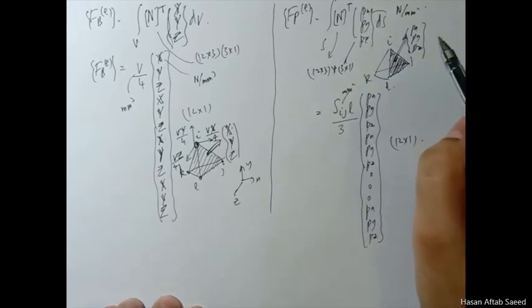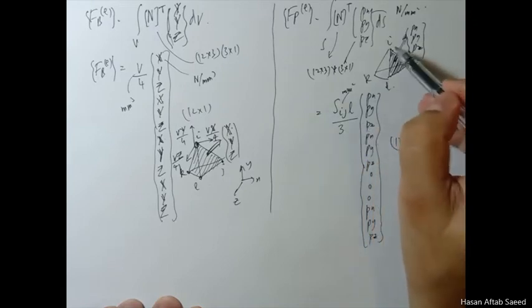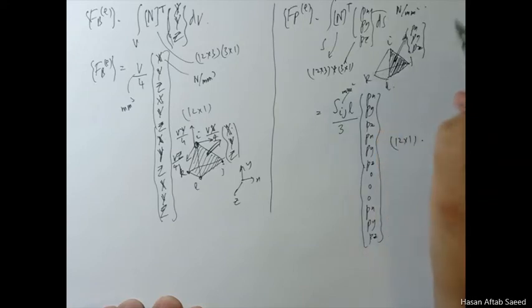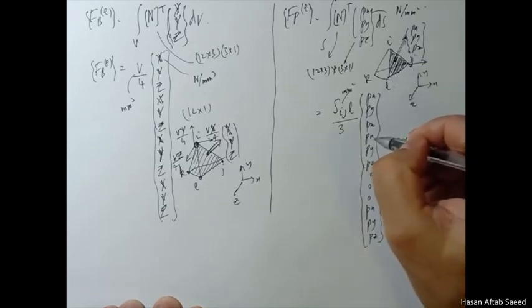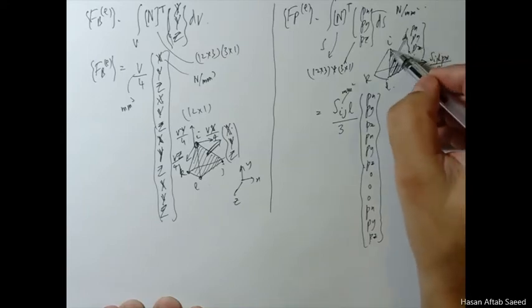Now the force you get in newtons in the x direction, you just divide by 3 and apply equally to all these 3 nodes, and you don't apply it to the k node. Obviously it has nothing to do with it, it is an interior node. So what we're talking about here is, if this is your x, y and z component, then here the force you apply, this is j node. Basically you're talking about this point. So the j node, you apply force of Sijl into Px over 3. Similarly, I node, Sijl Px over 3.